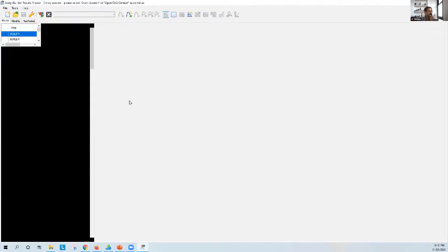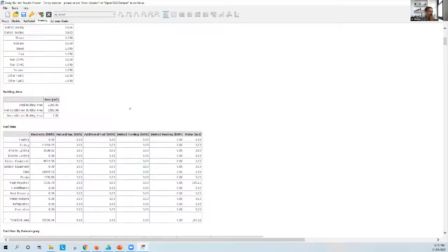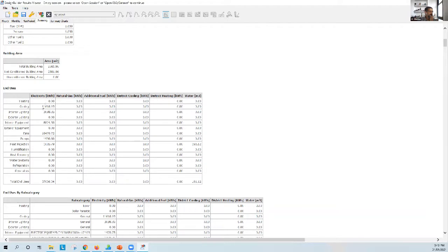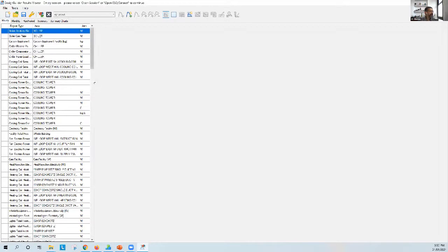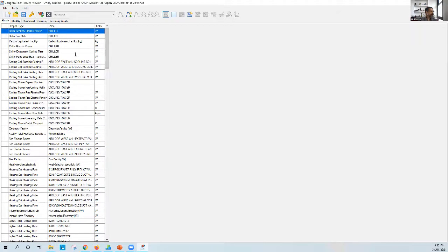And if I look at the summary, again, you can see cooling is 11,000 something. It's come down a little bit because now I've got 2 AHUs and it's able to control it a little bit. Fans have gone up a little bit because now you've got 2 AHUs and fans. The pumps and heat rejection won't change very much. You're still dealing with the same amount of load, okay? Old engineers will tell you, including myself, that load is load and you have to deal with the load. How you deal with it, sometimes it's a bit more efficient, sometimes it's a little bit less efficient, but there it is. So here's the chiller